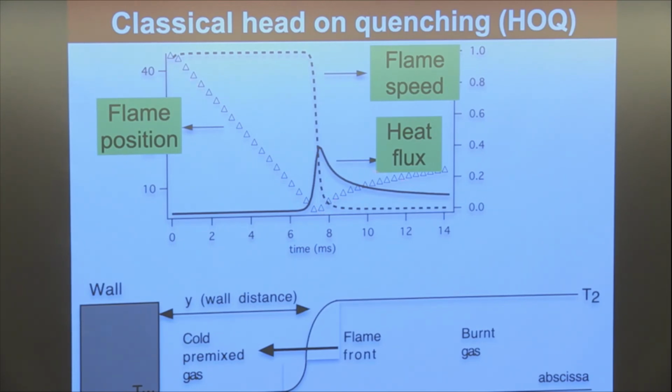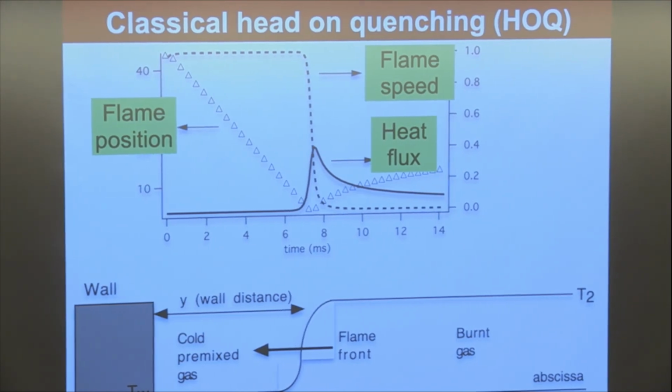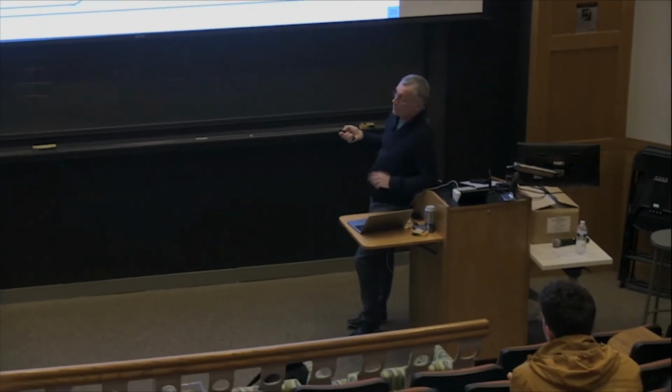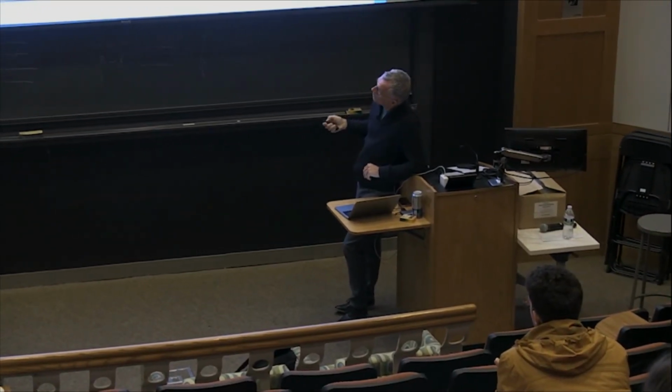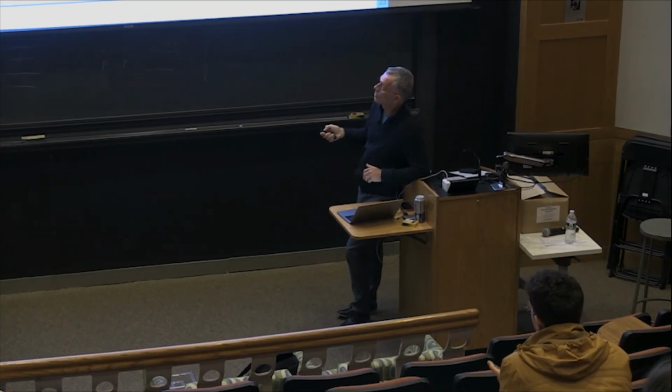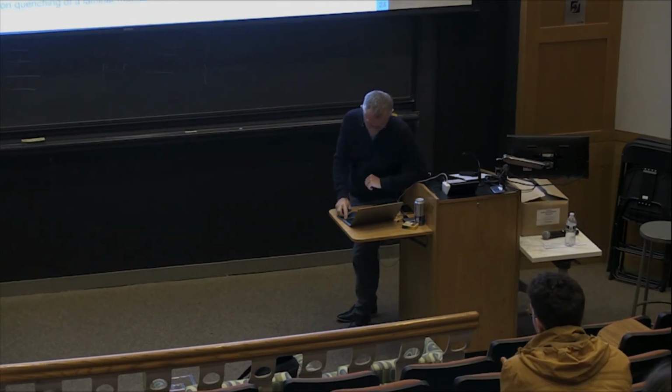So you can compute the heat flux through the wall, and this heat flux will be enormous. It's easy. If you don't believe me, just put your finger on the flame, you will see that it's a high flux. So we're interested in two things: the distance at which the flame can come closer to the wall, and the flux, which will be found in the wall.